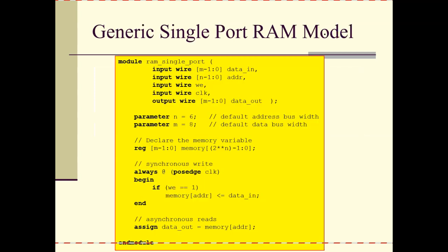This is the code for the RAM, and it's nothing super interesting here, but here we have the posedge, and anytime I use a posedge, that becomes a register of everything assigned in there, so that makes this memory a register.